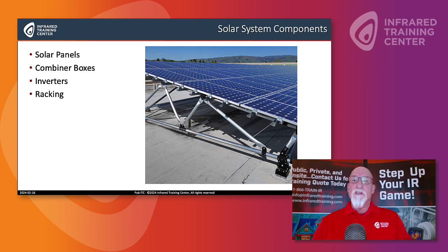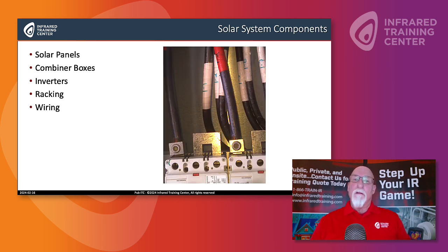The other thing, as you can see on this array, is that you need to be thinking about your acquisition angle onto the actual panel. So I'm going to discuss that in a little bit. What are we talking about with wiring and connections? Where are we looking? Now, if you take a look at these connectors, these conductors, we see that there's an insulating shield around the actual copper wire. That is a perfect place to find, if you do have a loose connection, that's where it'll present itself. It's on that shielding, not on the actual connection, which you can see down there is metal. And that metal is going to cause some issues with reflection.